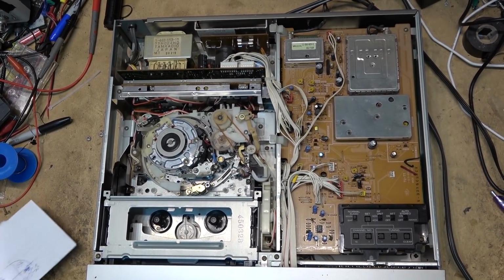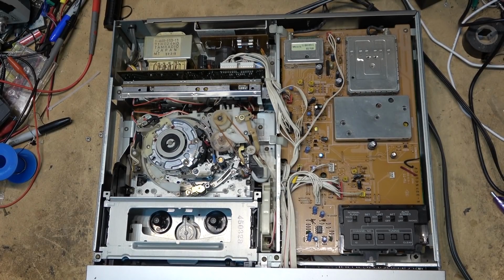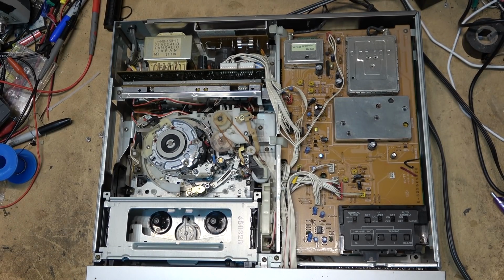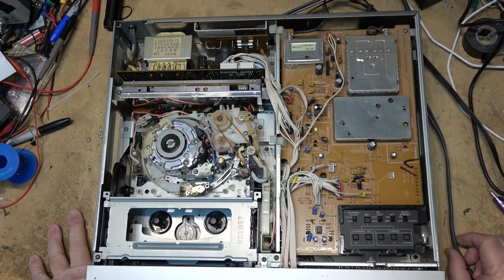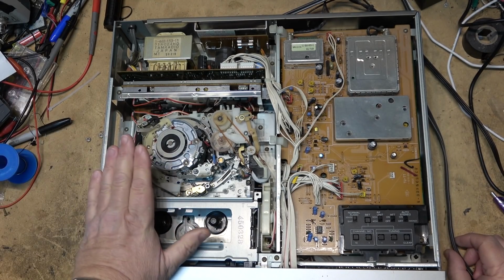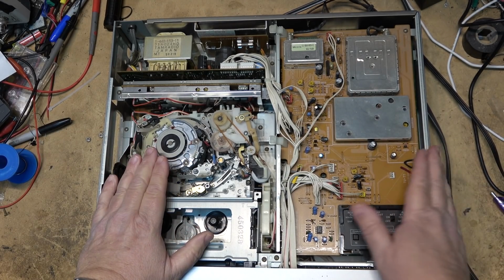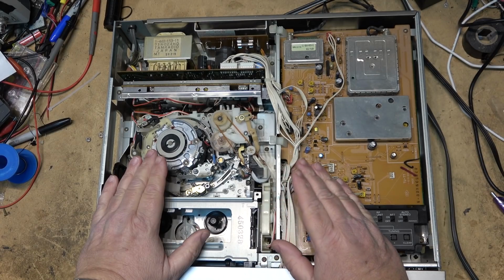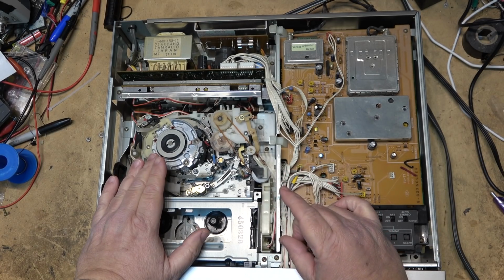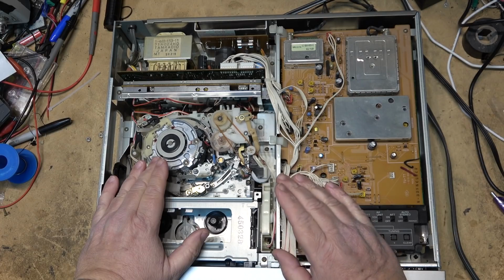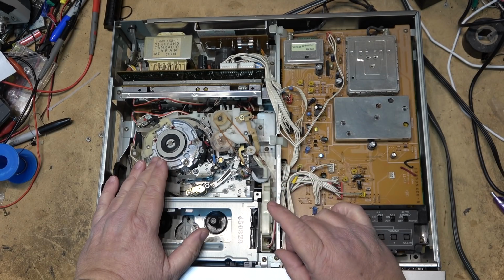Don't waste your time, because the frequencies I'm quoting here are something I remember from 40 years ago. It's nothing that we ever worried about in the field. I'm just trying to explain it so you understand what they did on Beta. They shifted the carrier up slightly for Beta Hi-Fi, but in the process they lost some of the lower sideband, and it degraded the picture ever so slightly. Not much, but it still did degrade the picture slightly.